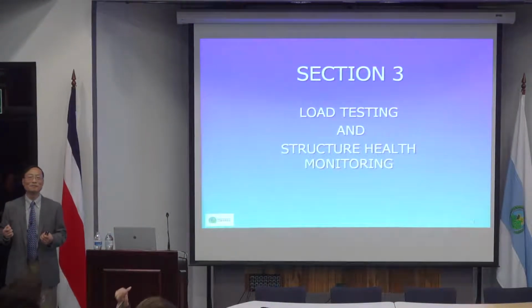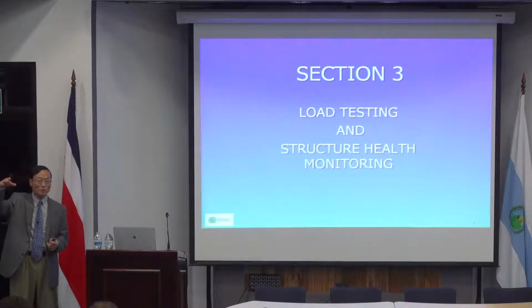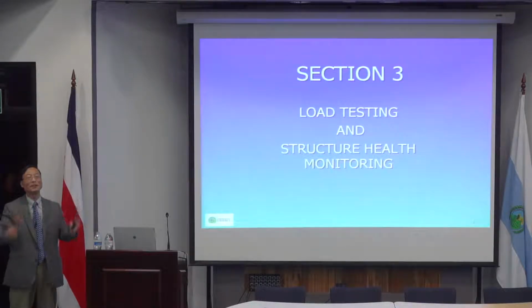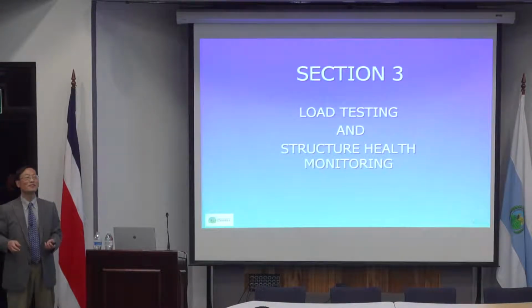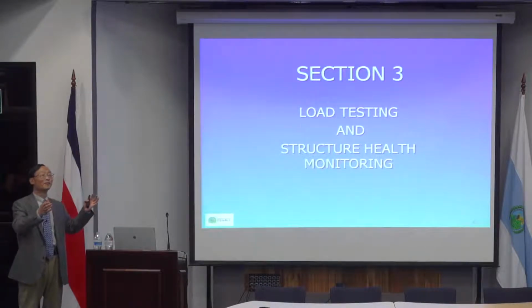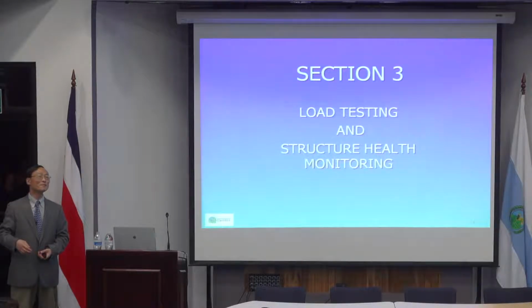We want to know, if, for example, we have multiple girders, when the truck comes to the bridge, how much the live load will be distributed into one particular girder under that truck. And the old AASHTO has an equation which simply says, okay, it's a function of the spacing of girder. The larger the spacing, the more load will be distributed to that. But that's just way oversimplified.